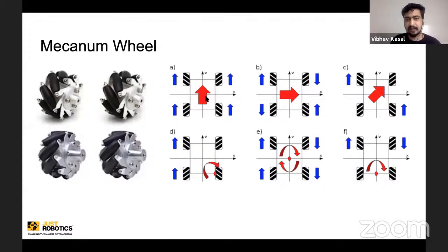When all of the wheels rotate forward, this robot will go front. Just look at the arrow marks, they will tell which motors have to rotate in which direction to get the lateral movements. So the robot, instead of going straight or taking a slight turn, is now going lateral, side by side, along the x-axis or y-axis.